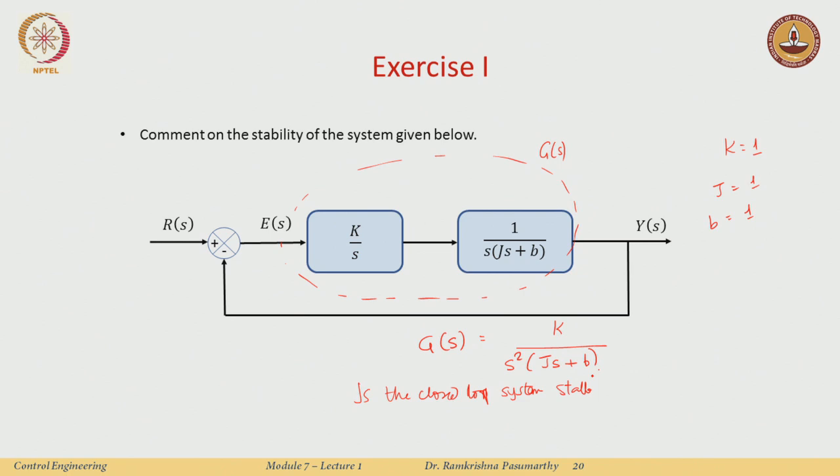Well, I can actually do the Routh analysis, but I will do the root locus, because now we are fairly familiar with doing that. Okay. So, where are the poles? Well, there is a pole here and a pole here, as at s equal to 0 in the sigma and j omega axis, or the complex plane. There is another pole at s equal to -1. Now, I think we now remember the rules of the root locus by heart. So, this branch will go here and we see that these branches actually go this way. We also did this particular example while we were doing the root locus plots, and you see that just adding an integrator here does not help me much, because the system is now becoming unstable. Okay. So, we have to be careful in that way.